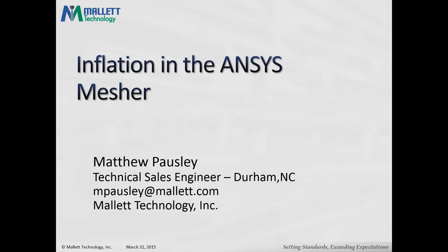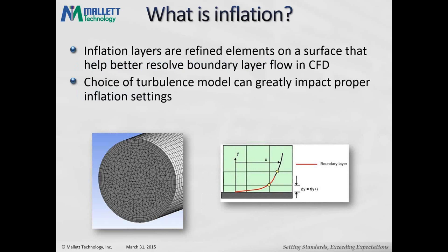Thanks, Dan. So we'll be looking at the various methods available in the ANSYS mesher for defining inflation for a CFD analysis. And just as a refresher, when we talk about inflation and inflation layers, we're talking about a method by which we locally refine the mesh on the boundary surfaces in a flow analysis with the intent to more accurately resolve the boundary layer.